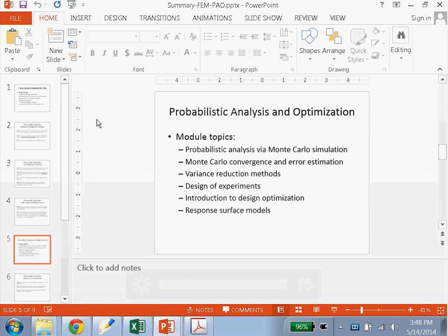We talked about the parameter study, the one at a time, orthogonal arrays, Latin hypercubes. So again, different DOE methods are different ways to choose which combinations of factors and levels. And then we also talked about the main effects, averaging over all the experiments with a factor at a particular level, looking at that compared to the average over all experiments. And remember the paper airplane experiment where we looked at the effects of the different design variable settings. That gives us some insight into our design space.